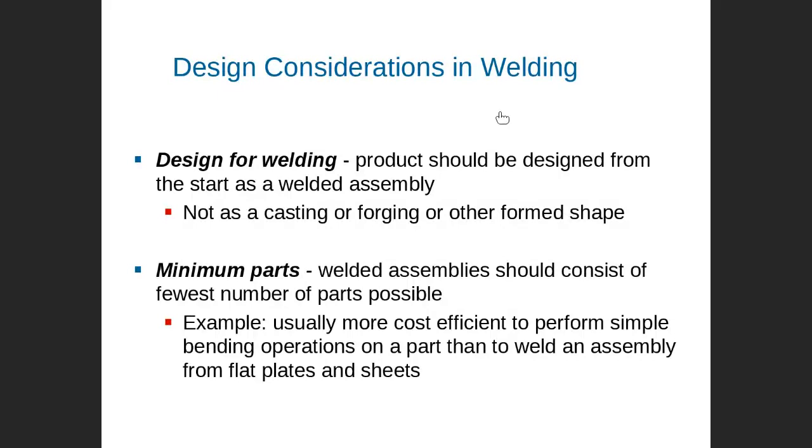The product should be designed from the start as a weld, not casting, not forging. As we described earlier, probably you do fixation for the part to avoid thermal stress, probably you heat the base material, probably you make tack welds to make it rigid, and so on. Probably you have to follow the recommendation of the International Association: speed, what filler material you use, what electrode, what flux is being used with this weld, and so on. It must be carefully designed.